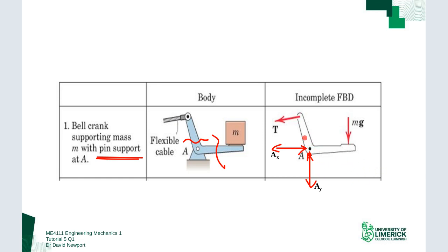The other thing is if I try and rotate it. So if I try and cause a rotation, in any direction, clockwise or anti-clockwise, just with that section, forgetting those loads, this pin joint will allow that rotation, so it is not going to react to it. And what that means is that I have no moment reaction there. But if I push it in the X direction or pull it, or push it in the Y direction, I would expect a reaction.